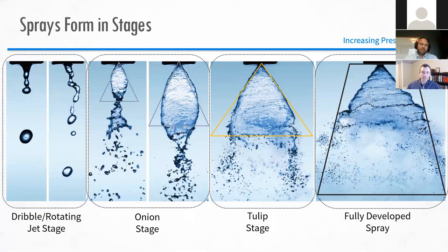And Kyle, you mentioned something pretty important. The characteristics of the gas or atmosphere we're spraying into can have an impact, particularly on certain applications, but also this dribble piece down on the far left-hand side. Imagine that big glob traveling at high velocity and hitting a turn in a gas stream. Not only the erosive effects that might have, but also the opportunity for depositing and corrosion as well. And I think that this visualization is very powerful for these process industry type folks.